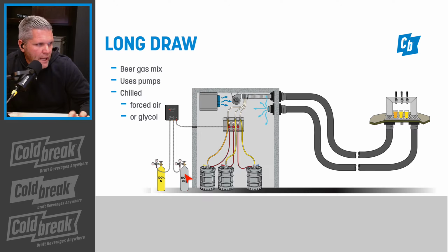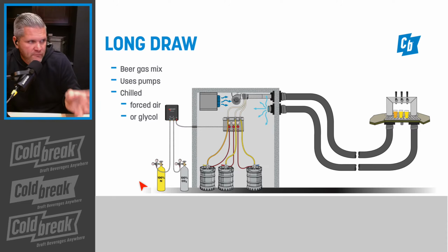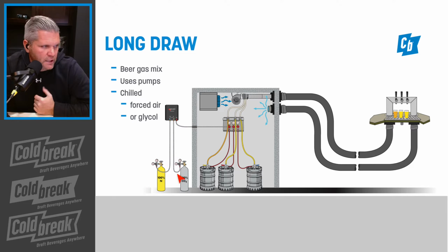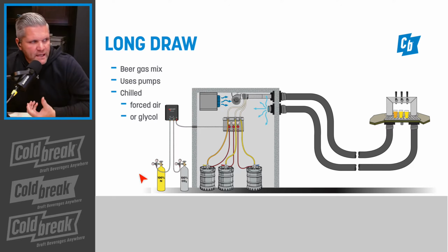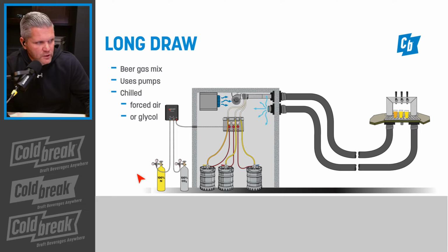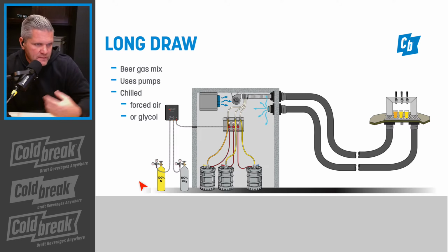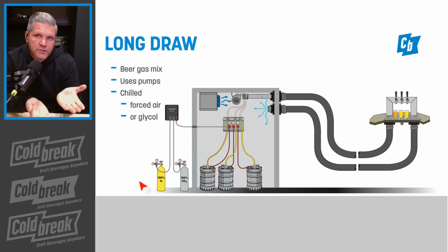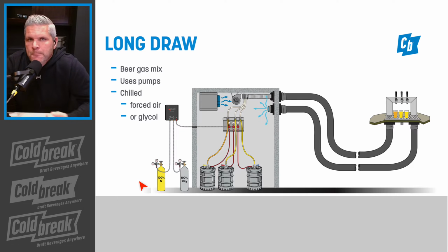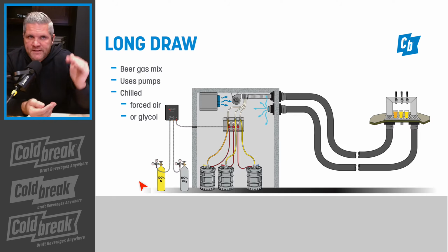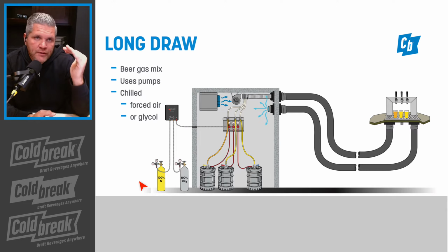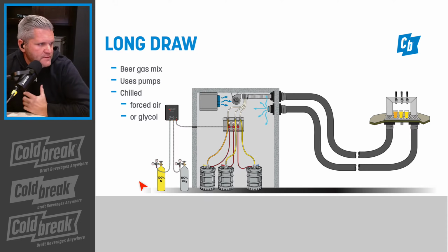When you add them together in a 5-pound tank, you wind up with a tank that can only dispense one keg of beer, because there's just not a lot of gas inside, since the CO2 will turn to liquid before the nitrogen can. There are some nuances in there that we'll get into a little more tomorrow.